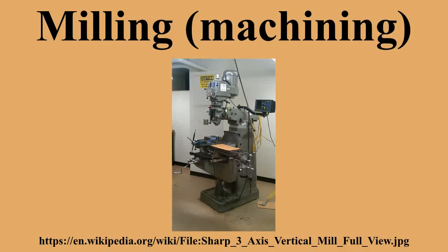Thus, vertical mills are most favored for die sinking work. Heavier and longer workpieces lend themselves to placement on the table of a horizontal mill. Prior to numerical control, horizontal milling machines evolved first because they evolved by putting milling tables under lathe-like headstocks. Vertical mills appeared in subsequent decades, and accessories in the form of add-on heads to change horizontal mills to vertical mills have been commonly used.